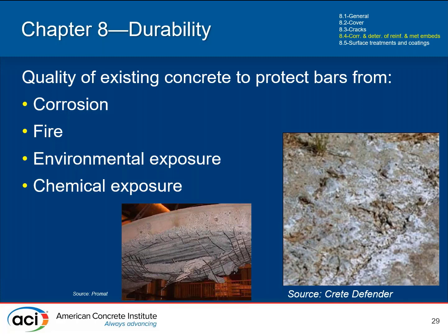Other concrete can kind of share the load, both literally and figuratively, to help out if some concrete is disappearing or having issues. There's a lot less redundancy in the reinforcing steel, so that really needs to be protected. So that's why we want to focus on the cover, and think about how that's going to protect things.